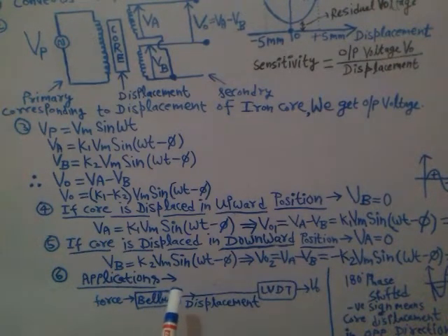By using a secondary transducer, force, weight, pressure, flow, and all such non-electrical quantities can be measured using an LVDT, right? For example, using bellows as a primary transducer, we can convert force into displacement. Using bellows or a Bourdon tube, we can convert force into displacement.